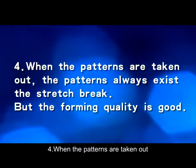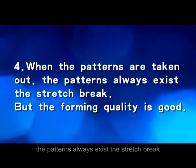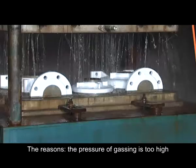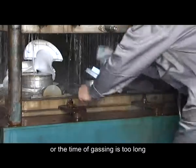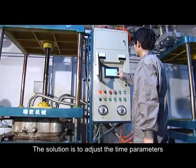4. When the patterns are taken out, the patterns always show stretch breaks, but the forming quality is good. The reasons: the pressure of gassing is too high or the time of gassing is too long. The solution is to adjust the time parameters.